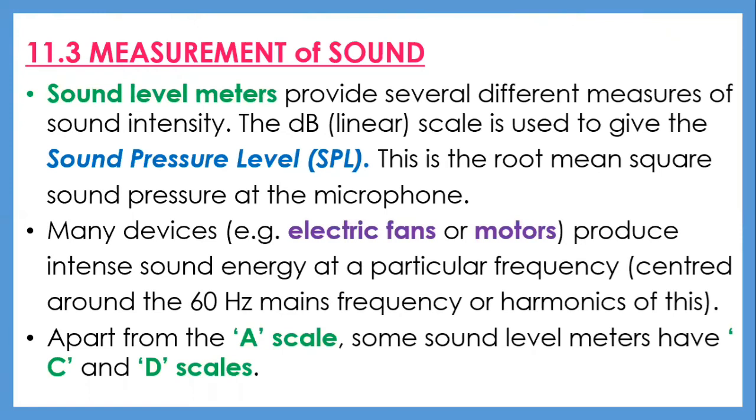Now here, when sound is measured using the dBA scale, a weighting network selectively amplifies or attenuates different frequencies, similar to adjusting the tone control on a modern hi-fi amplifier. The sum of the pressure levels of the various frequencies is called the sound level, or LS.